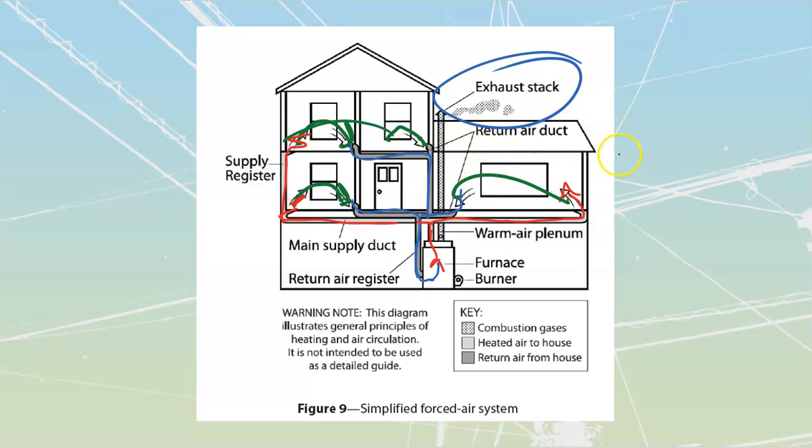What you would want inside of a house like this, though, is that there always has to be an introduction of some fresh air back into that. These are sometimes going to be done through external fans. I don't know if you have done standalone dwellings, but you're usually going to have one exhaust fan that's going to be on a humidistat timer upstairs, and that's going to run cyclically.